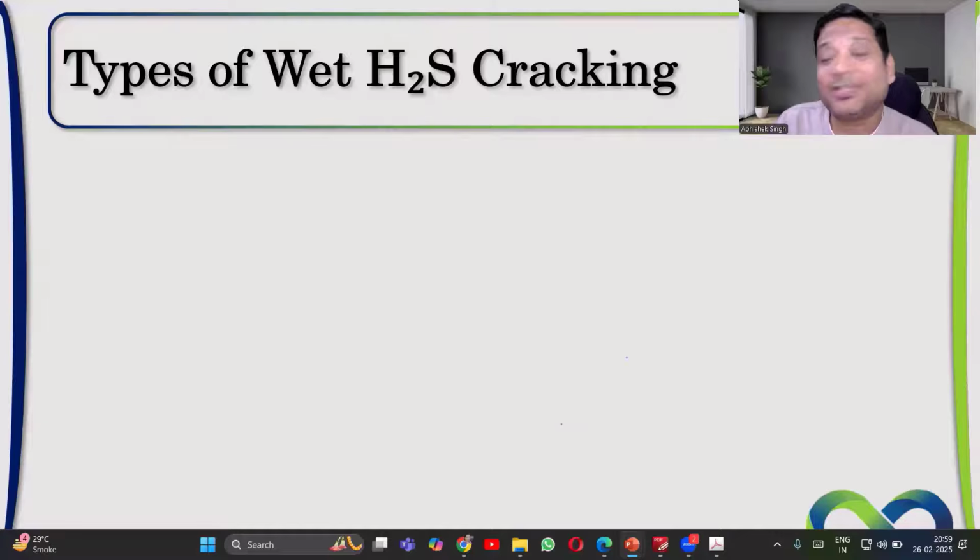Now, types of wet H2S cracking. What do you think are the common cracking phenomena in H2S service? Give me that in chat. SSC, we talked about that. SSC is sulfide stress cracking. Blistering, very good, hydrogen blistering. Then HIC, hydrogen embrittlement. Then you have SOHIC, stress oriented hydrogen induced cracking.